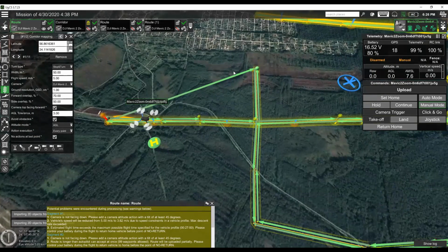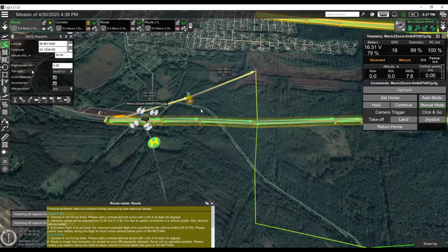To create additional waypoints between these two lines, you have to select the segment after which you want to insert them. So here are two segments, and I am selecting the first. If there were, for example, 4 segments, and you wanted to insert between the third and the fourth segments, you would have to select the third segment, then select the waypoint tool and create additional waypoints.